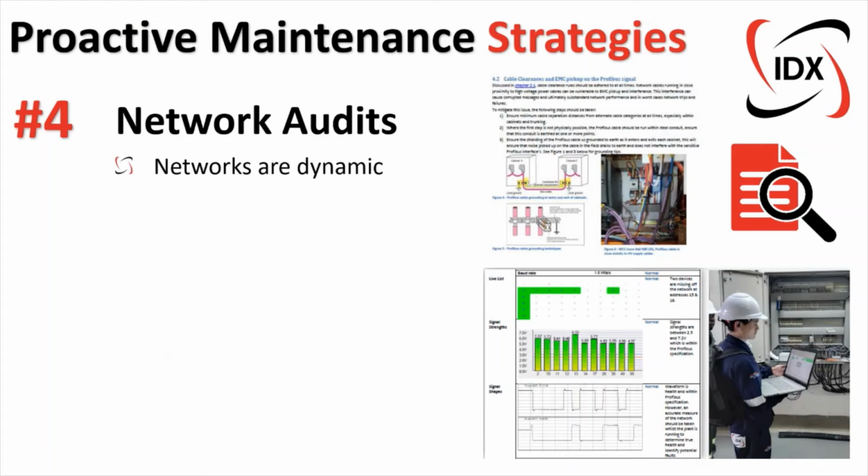So what a network audit should be basically doing is saying at this point in time, the network was installed according to PROFIBUS specifications and guidelines, and the network has a high availability. But because networks are dynamic, this network audit should be repeated over and over again. How often or how frequent that is, I suppose it depends on your site.